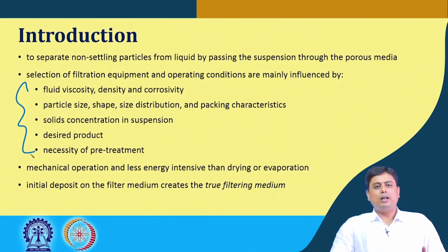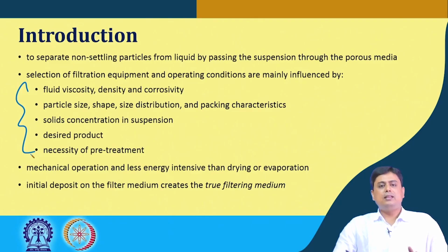Now, is there any necessity of pre-treatment of the suspension? If pre-treatment is required, then the consequent filtration equipment can also be changed for an optimized result. Pre-treatment means, say, heating the suspension beforehand, or adding some coagulant to the suspension to make flocs.